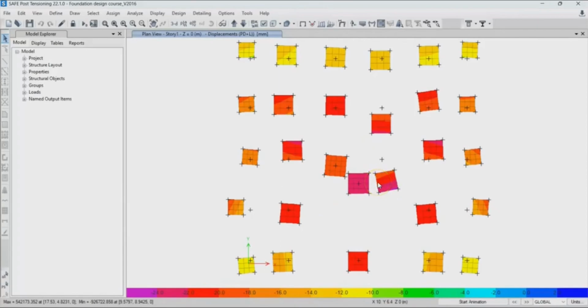Instead of keeping them as single isolated footings, you can simply merge them into a single continuous combined footing. Okay, so this is going to prevent the differential settlement for this footing. Or, if you find that even after providing the combined footing you are still having differential settlement, what you can do is improve the ground. You can change your subgrade, you can change your soil subgrade modulus. So that is where you have to contact your geotechnical engineer.